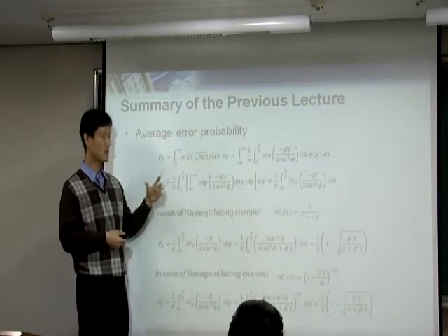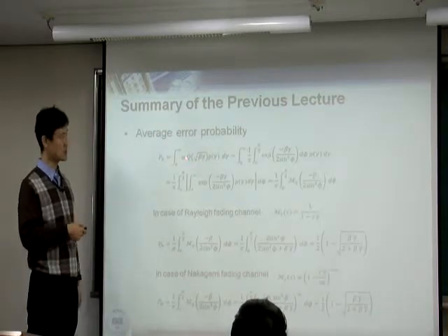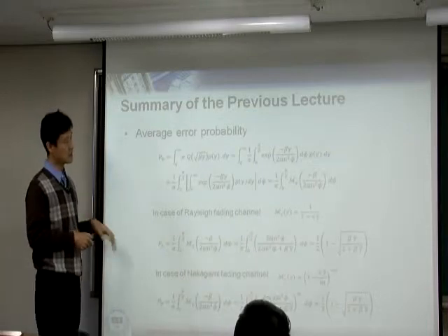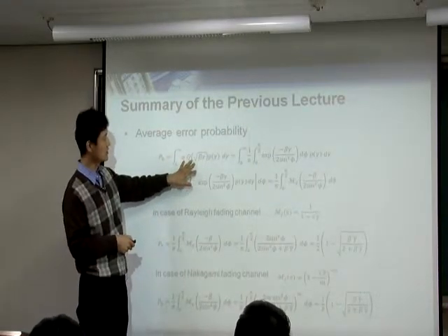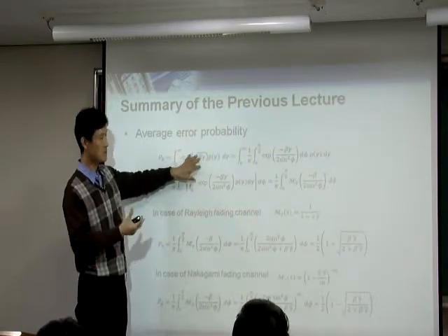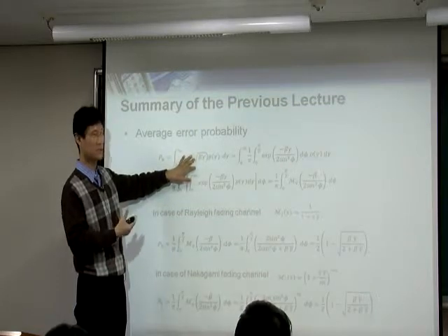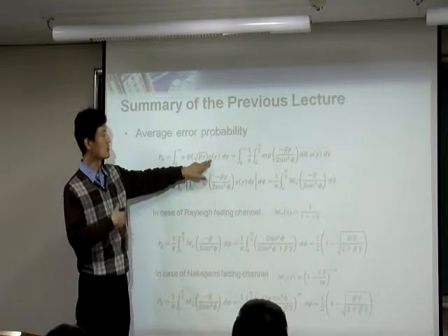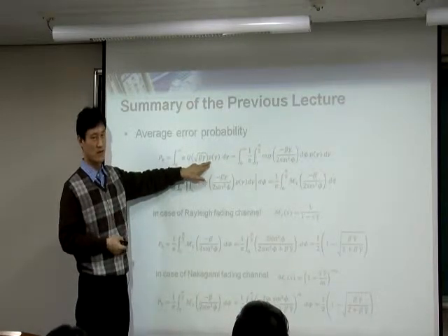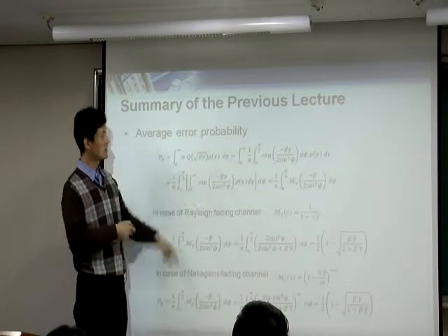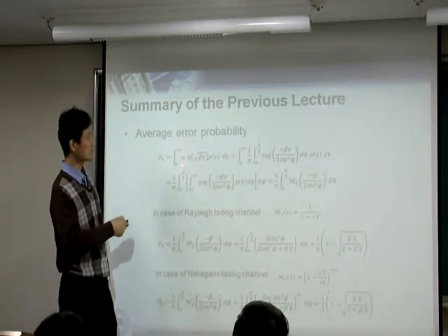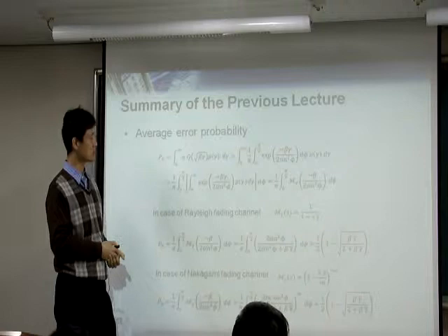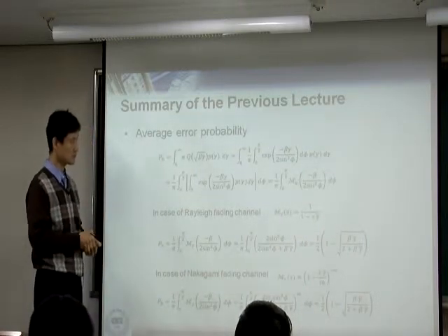Although this is a very close approximation, pretty tight to the actual BER, so it's very popular to use this one. So this is a general bit error rate approximation of any modulation. And then you use your own fading profile, Rayleigh or whatever. So in that sense, this integral equation is a generic performance analysis equation, okay?